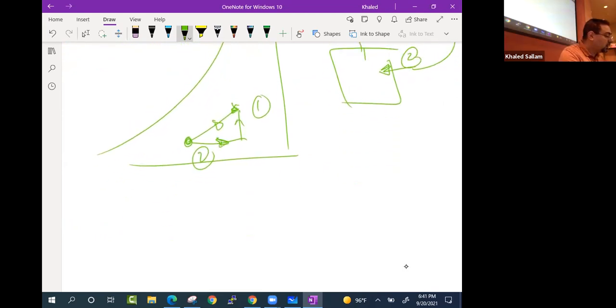Two parts, right? A part that gets the air more humid and a part that gets it hot in the heating, like in the cooling application. So this is because we just need cooling, and this is because we just need drying, right? So this is the latent cooling, and this part is the sensible cooling.